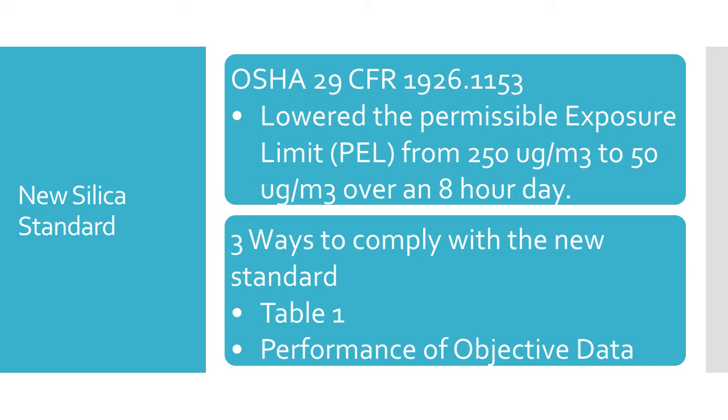The last way to comply would be to conduct personal air sampling of employees during the activities they perform and use that data to select the appropriate controls needed if the exposure exceeds the PEL.